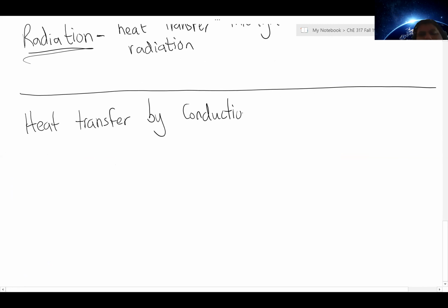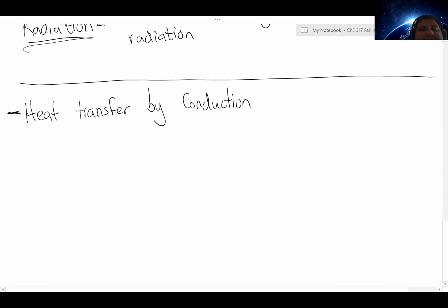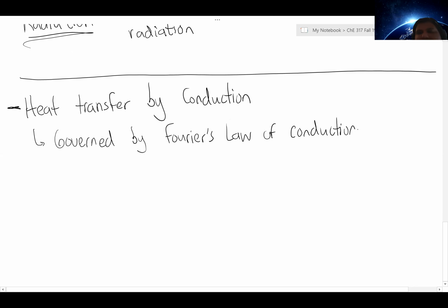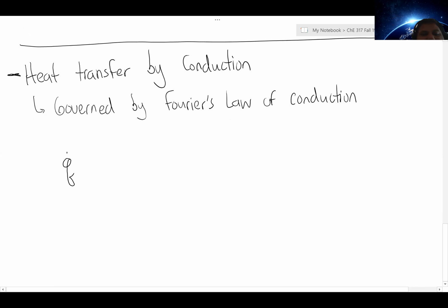So conduction, as I said, is heat transfer due to direct contact, and it's governed by what's known as Fourier's law of conduction. And Fourier's law states that the heat flux through an object is equal to the driving force, or excuse me, the temperature gradient that exists in the object, multiplied by a constant of proportionality.